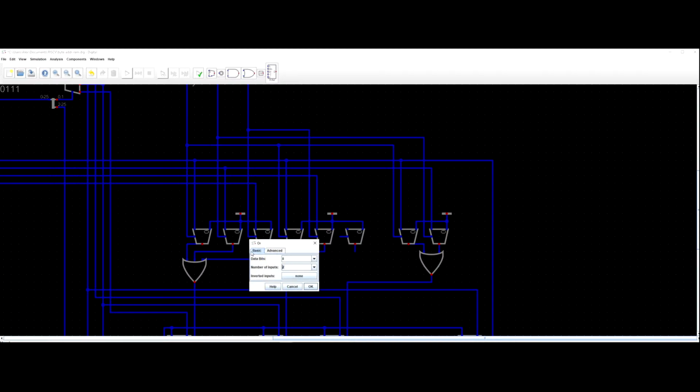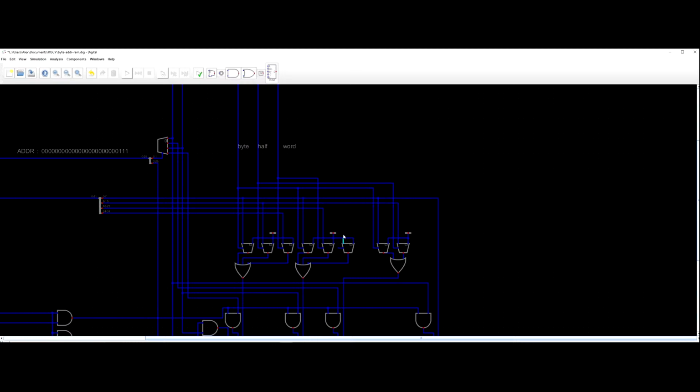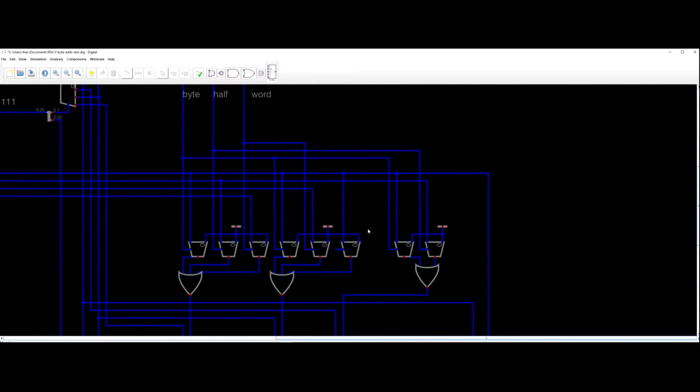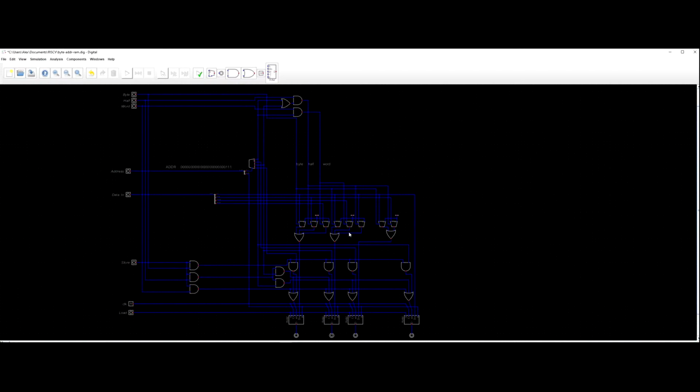So we need 3 inputs on this. Shift that over. And now we gotta allow the low byte in. Oh yeah, 1, 2. Yeah, I did it on every other one but this one. Wow, okay. And then when half is true, that's what gets loaded. This should have fixed it.